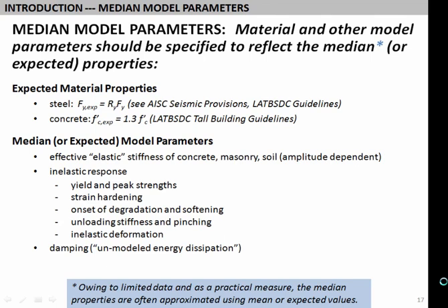When you look at deformation capacities, when you're putting in hinge rotation backbone curves, these things should all be kind of like the average value, if you will. So we want to be starting our analysis from capturing kind of the average behavior and then think of things from there. This is kind of contrary to what you might do in certain practice, where our tendency as structural engineers is to, quote, be conservative, given a lower bound on the stiffness. But the idea when you're combining shear walls and frames and other elements and everything, what's conservative is really unclear. So the key message here is, for every modeling parameter that you put in, think of that being kind of an average value to start with.